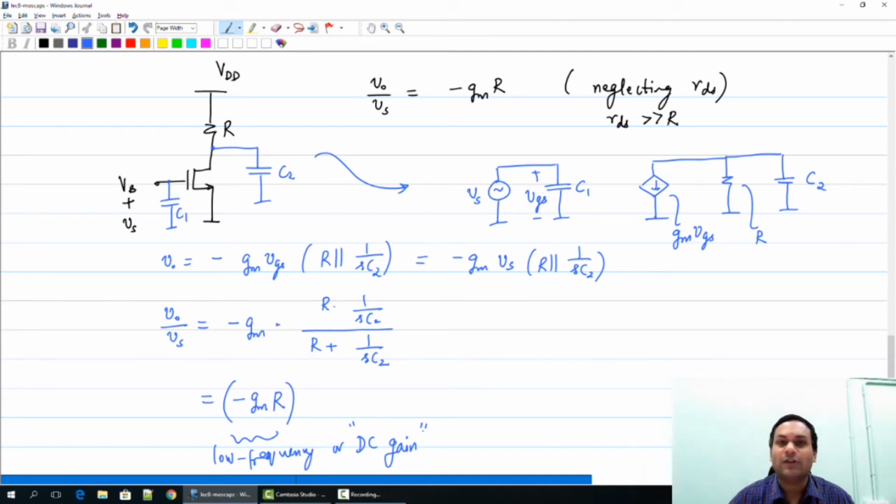It is the low frequency gain of the amplifier, and that is of course multiplied by 1 plus SC2 R2. This gives you the frequency response of the circuit, which happens to go to 1 when you operate at very low frequencies. Now, as you can see in this particular case, the transfer function, which is the gain of the device, has a single pole response.